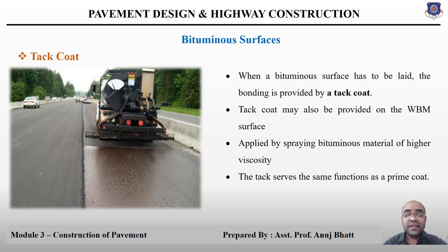Here I must say you have to remember the rate of application. This can be asked in short questions or in MCQs: at what rate the bituminous material or bituminous liquid is to be applied for the prime coat and for the tack coat.